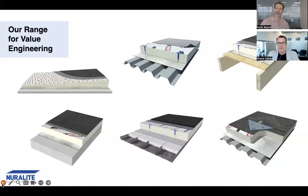Yep, no, that's right. This slide here, we're just trying to illustrate that we have multiple options when it comes to cost-conscious roof design. We're not a one-trick pony, and there's several factors to consider. One is to look at the actual membrane type, whether we're using a single layer or double layer. So factors that would sway you one way or the other is, is it a suitable project to be using an open flame or not? Is it a simple rectangle project with large square meters where it's simple to lay a single ply? Is it a construction site that's going to have heavy foot traffic and therefore it should be double layer? So those are things to consider, and they will actually have an effect on the cost.